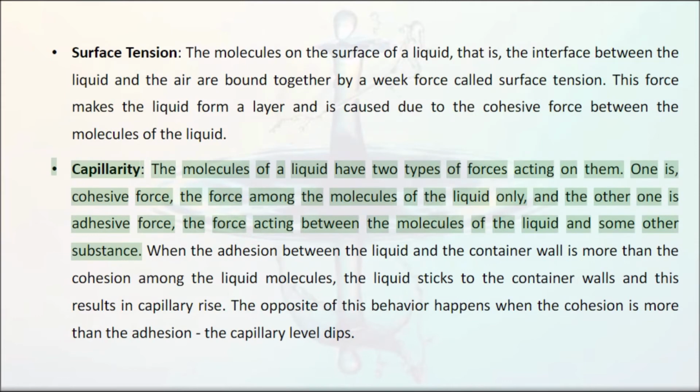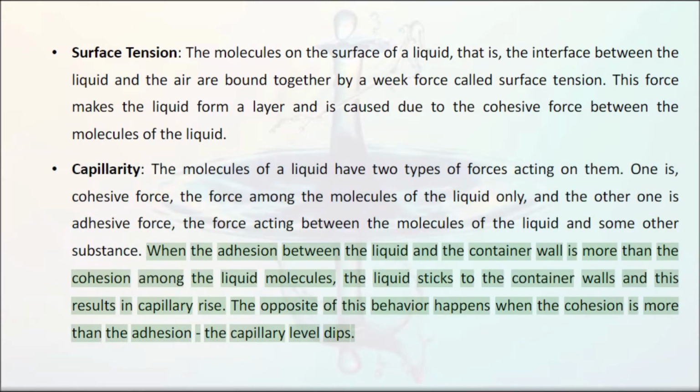Capillarity: the molecules of a liquid have two types of forces acting on them. One is cohesive force, the force among the molecules of the liquid only, and the other is adhesive force, the force acting between the molecules of the liquid and some other substance. When the adhesion between the liquid and the container wall is more than the cohesion among the liquid molecules, the liquid sticks to the container walls and this results in capillary rise. The opposite happens when the cohesion is more than the adhesion: the capillary level dips.